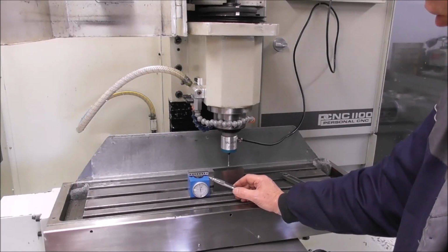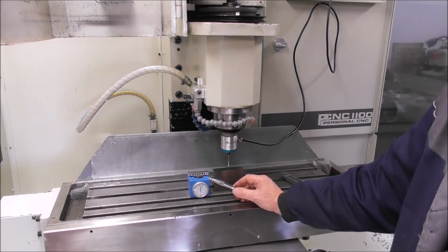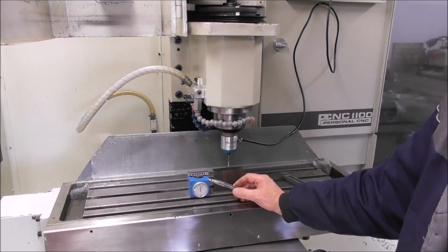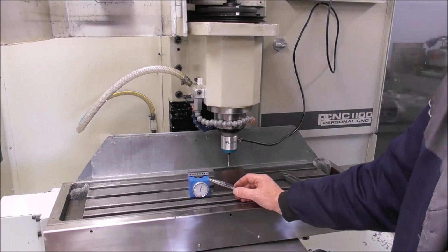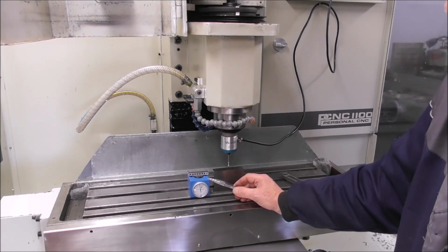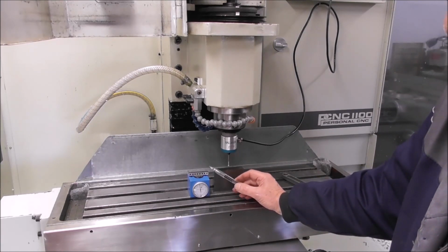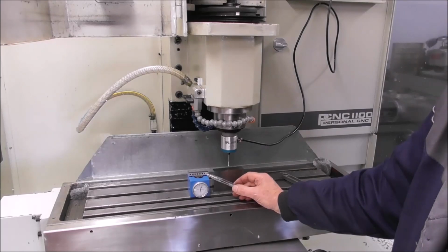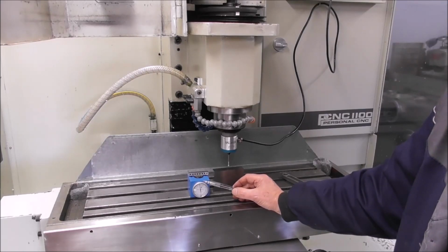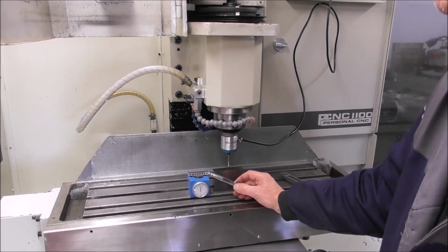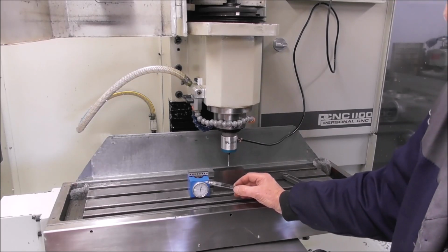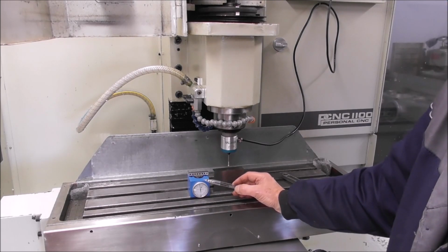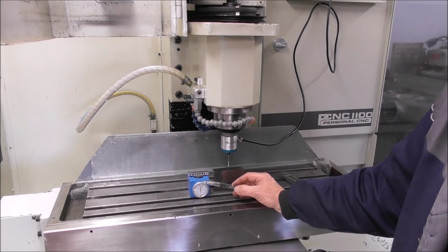So you can probably see with this example that this type of dial indicator tool length setter is quite convenient and quick, because we're usually only concerned with setting the Z length of the cutter, the tool height. So we just come down until we're at 0 on the dial, and then just push a button and it loads the tool length into the tool table. So that's fine. So you could argue that you don't really need an electronic tool setter to do that automatically for you, because it's just pushing one button.